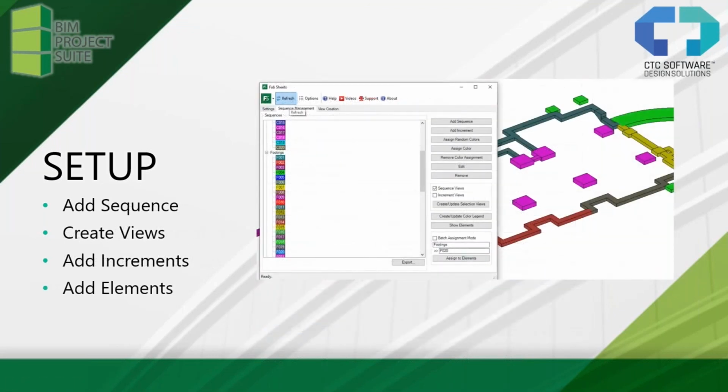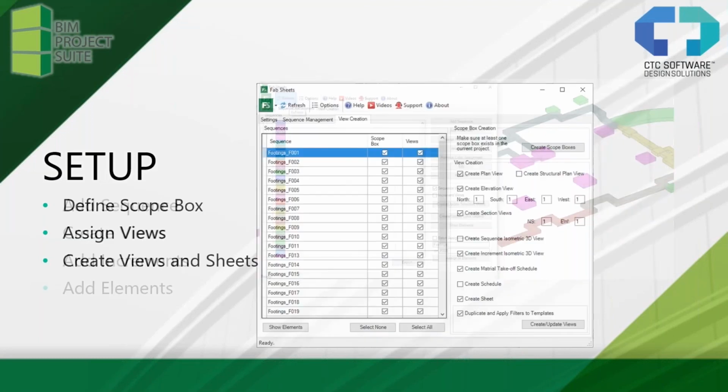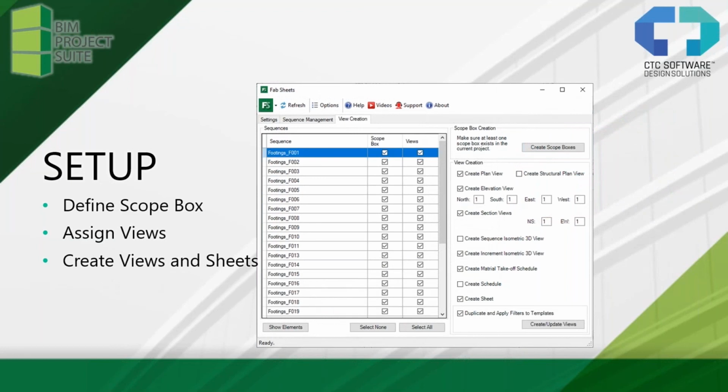And then the next set is where we set up the sequence and increments themselves. So you go through, if you're doing footings or slabs or walls or columns and beams, right? You create the sequence and the increments for them, create the views, assign the elements to a particular increment, and then move on to the next phase. So this area here is how we are applying the settings to a grouping of elements in our model.